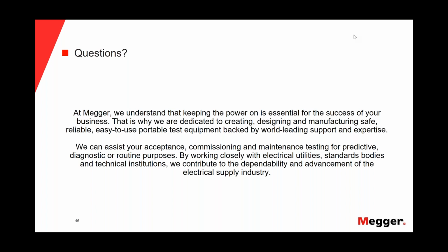All right, thank you, Javier. And then I have a question for Sergio. Sergio, what is the preferred: cosine rectangular or DAC? Really depends on what it is that you want to do. If you were doing, as mentioned before, commissioning testing and wanted to perform the VLF or monitored withstand test at the same time, you would use a VLF with the cosine rectangular for your commissioning test so that you're performing both tests at once.